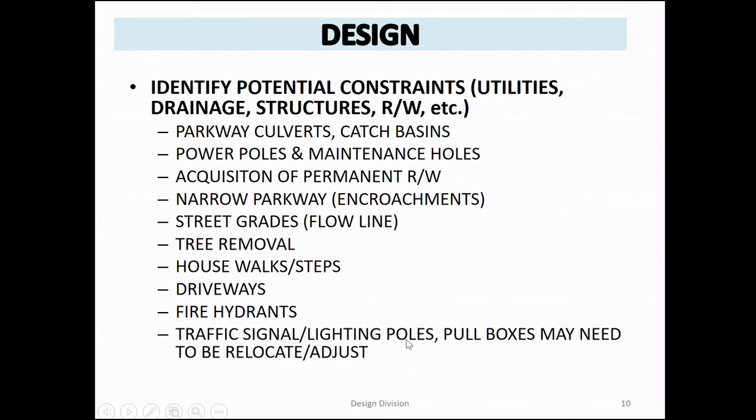Any questions? Yes. Does it have to have a certain space for the level landing? TNL will take care of that, but yeah, it does. I think it's about 24 inches. Yeah. So it has to be on a level surface. If they can reach it from the slope part of the ramp, that doesn't count. Because of the width of the flare, I don't think it's too far, yeah. By level, do you mean like 1.5%? Yes.